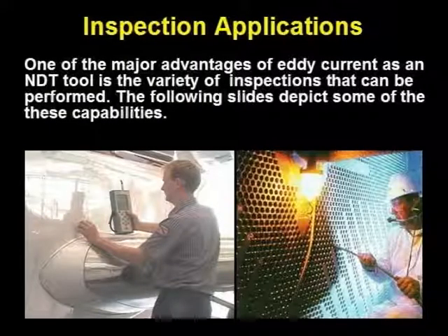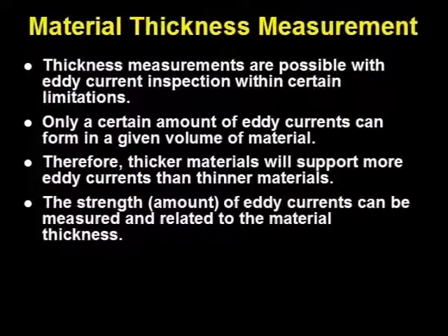Eddy current inspection can be used for a wide variety of applications. The left image shows crack or corrosion inspection on an aircraft. The right image shows inspection of heat exchanger tubing. Thickness measurement is one application for eddy current testing.